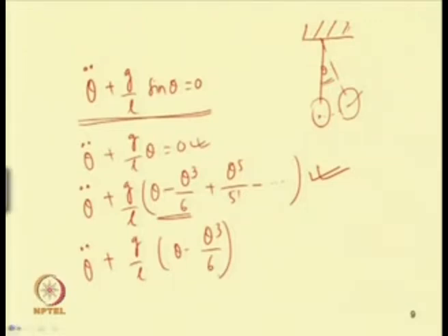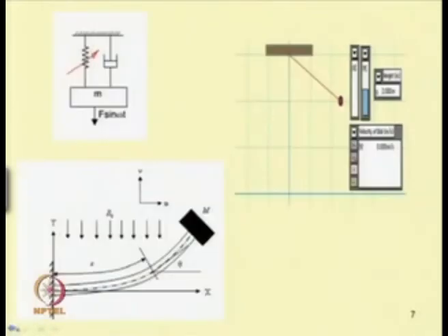In these conservative systems, one can study the solution either by doing qualitative analysis or by doing quantitative analysis. In case of qualitative analysis, one can find the potential well of the system, and from the potential function one can find the type of response, or one can plot the phase portrait and find what the response will be.